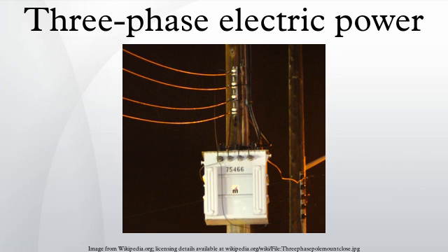Generation and distribution. At the power station, an electrical generator converts mechanical power into a set of 3 AC electric currents, one from each coil of the generator. The windings are arranged such that the currents vary sinusoidally at the same frequency but with the peaks and troughs of their waveforms offset to provide 3 complementary currents with a phase separation of 1/3 cycle. The generator frequency is typically 50 or 60 Hz, varying by country.